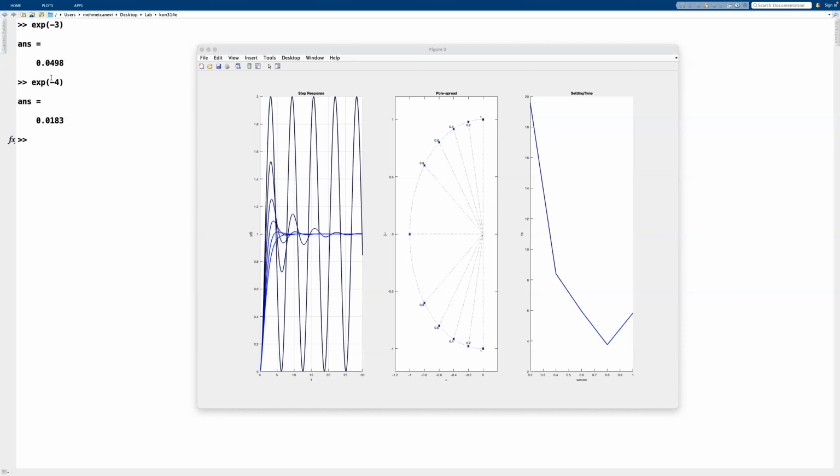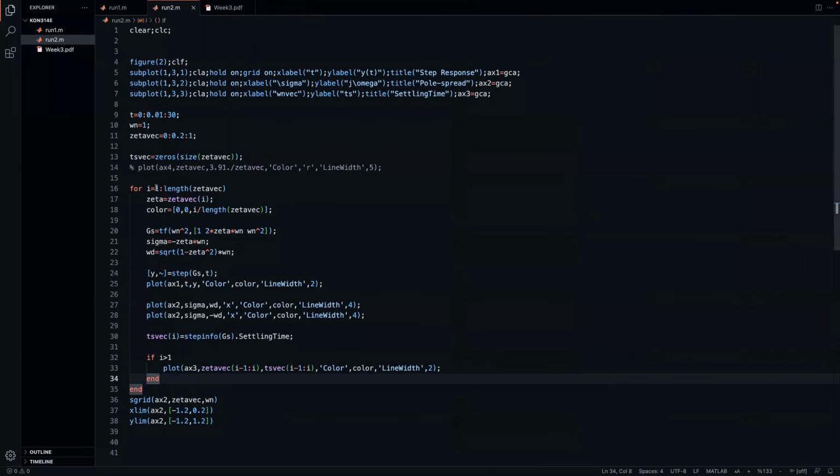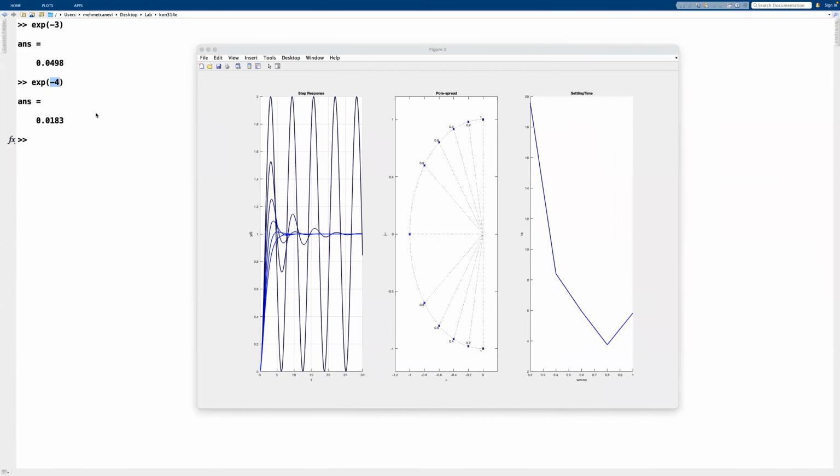So therefore, what it does is it just takes the real part of the poles, which is sigma, which is zeta times omega n, and uses that to model the settling time of a second order transfer function, which is seemingly the same as for the first order system. So you get basically -4 equals minus zeta times omega n.